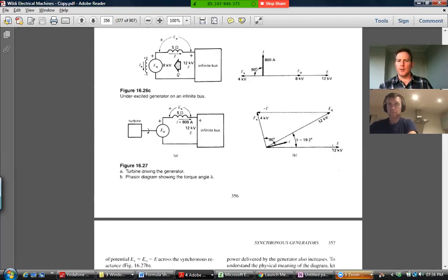Okay, but yeah, this number here will not be the grid voltage as specified, because when you specify grid voltage, you'll be saying line to line. So you've already divided by root 3 to get this vector here. Okay, because you're analyzing it per phase.